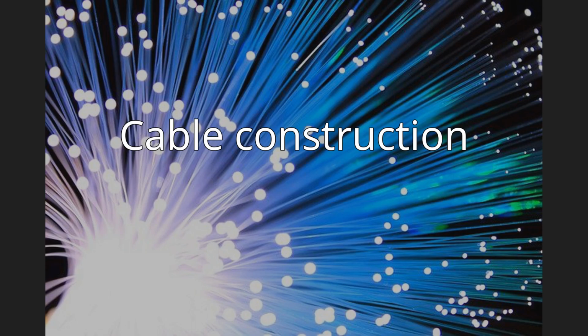Cable construction. In practical fibers, the cladding is usually coated with a tough resin coating and an additional buffer layer, which may be further surrounded by a jacket layer, usually plastic. These layers add strength to the fiber but do not contribute to its optical waveguide properties. Rigid fiber assemblies sometimes put light-absorbing dark glass between the fibers to prevent light that leaks out of one fiber from entering another. This reduces crosstalk between the fibers or reduces flare in fiber bundle imaging applications.